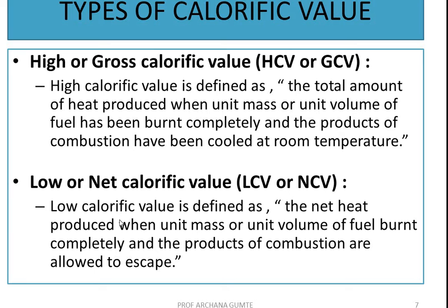Similarly, let us focus on low or net calorific value. It is the net heat produced when unit mass of fuel is burnt completely and the products of combustion are allowed to escape. Therefore, you have to remember the major difference between HCV and LCV. For HCV, the products are cooled to room temperature, and here the products are allowed to escape.